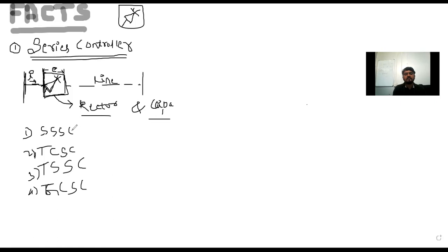Like this, so many devices are there. Thyristor controlled voltage regulators and phase angle regulators are there. Resistance and reactor we can also control, that is, the thyristor switched series reactor, TSSR, we can also use.